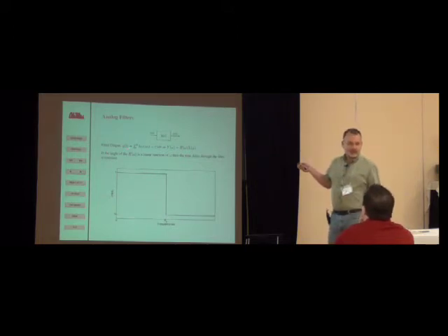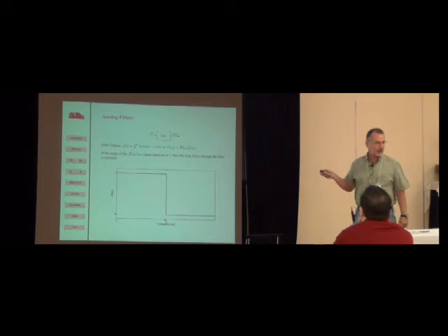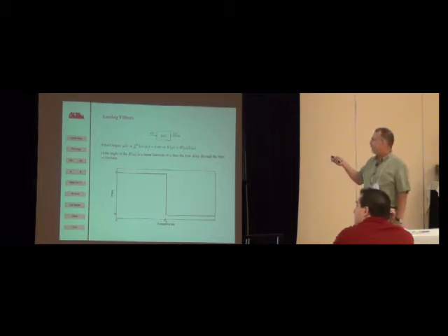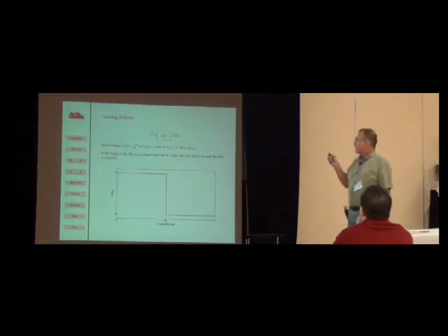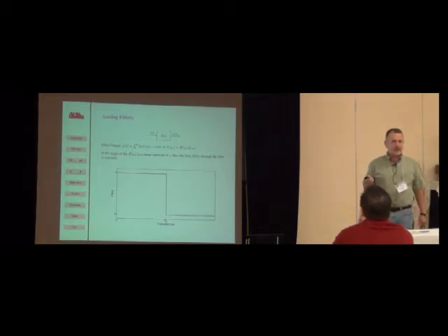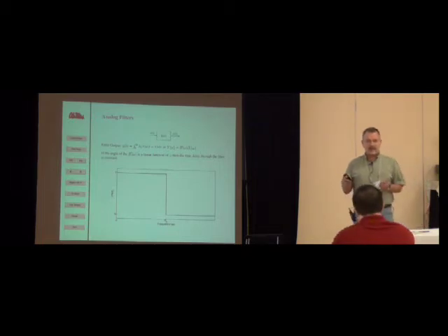We're usually interested in looking at filters in the Fourier transform domain. So if you take the Fourier transform of this convolution relationship, you get this. Capital letters are the Fourier transforms, and this H of f is the transfer function of the filter. Usually in signal processing, you want a filter that has a time delay that's independent of the frequency component of the input. This is so that you don't get distortion of time domain pulses through the filter.